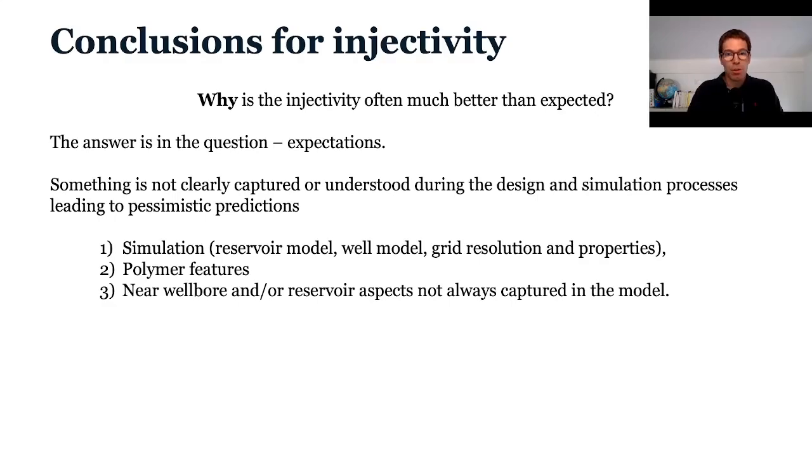In simulation, many people don't want to see or don't update the model to take into account the fractures or the extension of perforations versus time because of the water quality or these aspects. So it's something which is moving, because if you inject polymer, you might extend the fracture. If you decrease the viscosity, it might close down. If you increase viscosity, it might open up. So it's something very dynamic that should be monitored and understood, and then maybe put into the model.